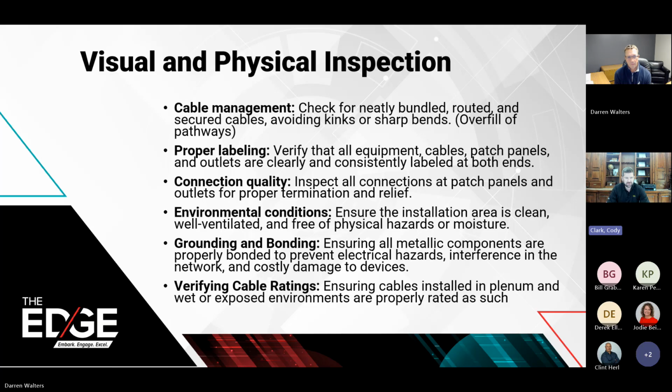Grounding and bonding, like we just talked about. One of the big ones there is if you're in a hospital system or somewhere where you're using a shielded cable solution, if they have not properly grounded that cable, it'll actually end up causing you negative impacts on your network instead of improving the performance of it. So making sure that's done properly, and then verifying your cable ratings.